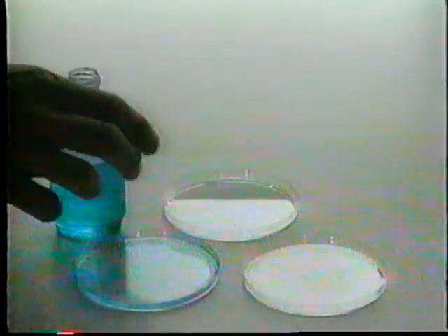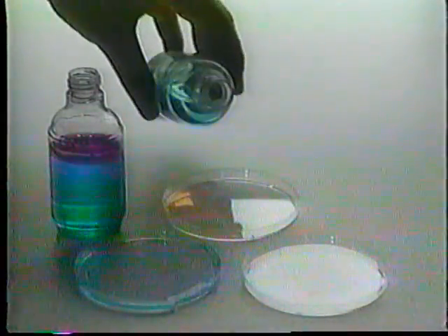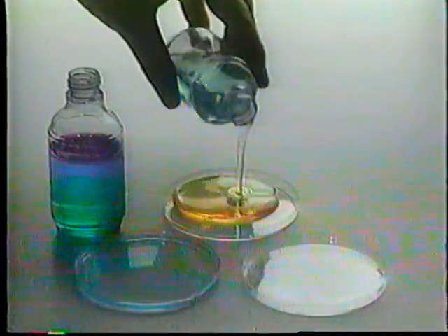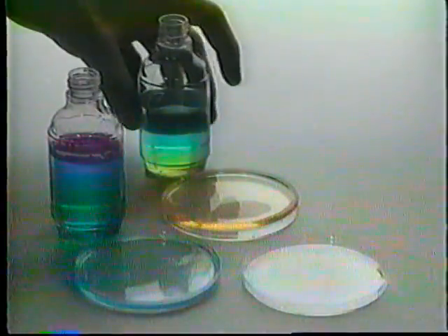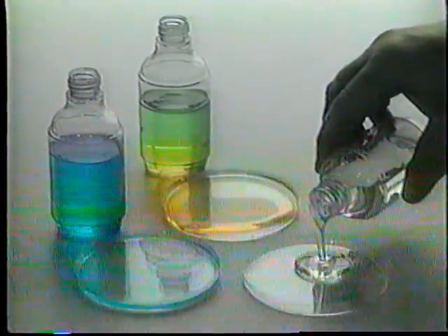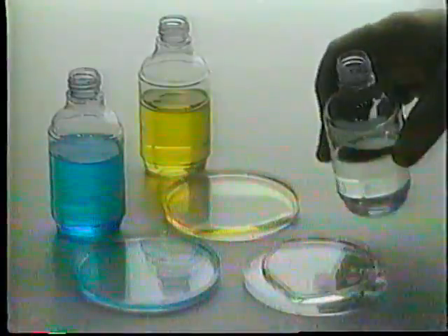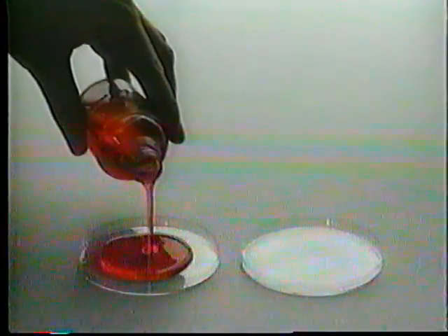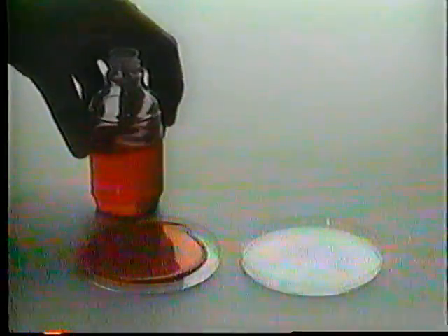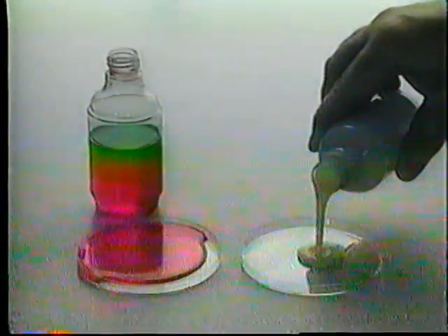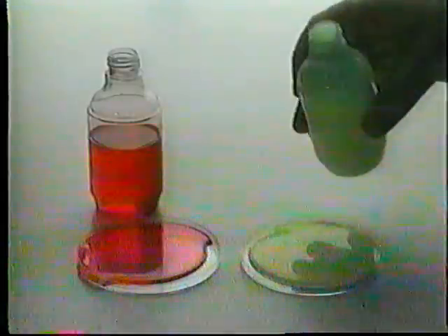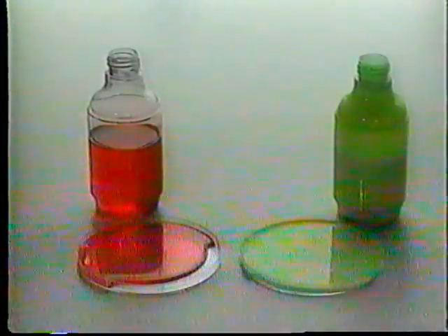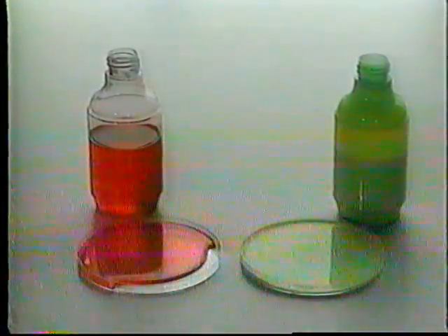Synthetic oils are made completely by chemical manufacture. There are many different kinds, but polyalkylene glycols, polyalpha olefins, and silicones are probably the most popular. Finally, there is a group of fire-resistant oils, typically hydraulic oils like the water glycols and invert emulsions. These are often used where combustible materials would cause a hazard, for example, in foundries, coal mines, or steelworks.